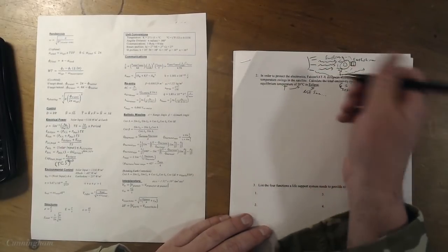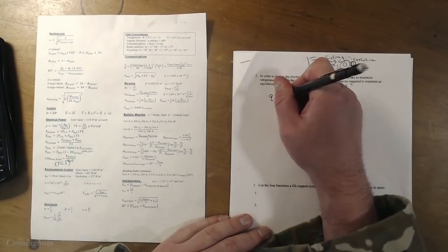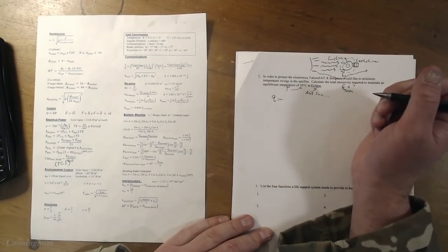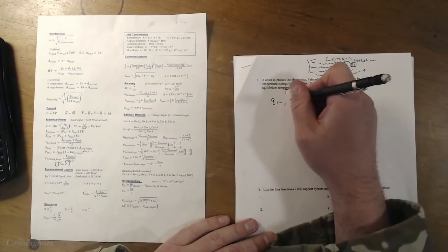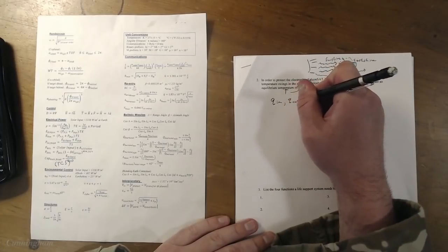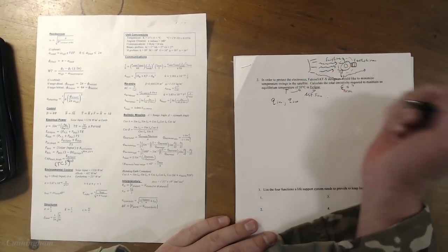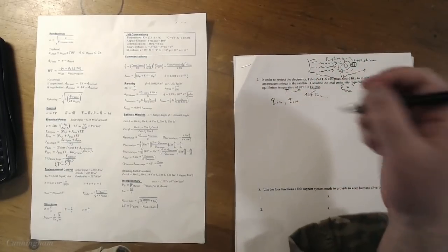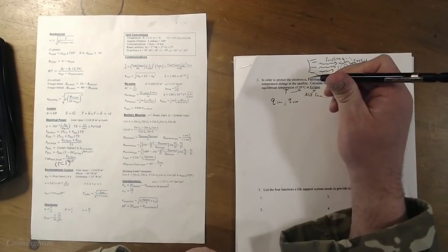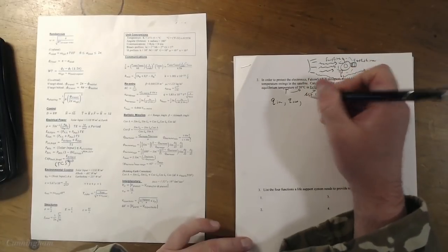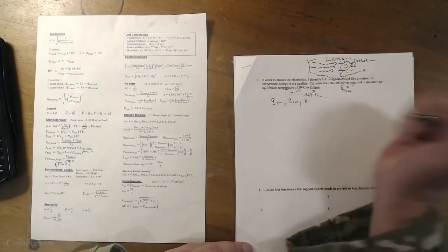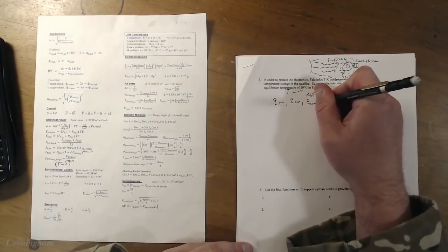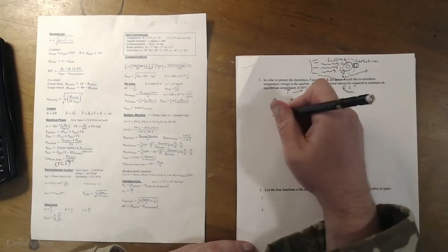So let's begin. Our process looks the same. We're going to find how much heat overall is coming into the satellite, how much heat needs to go out from the satellite, because remember, Q out takes into account all the heat generated by the onboard electronics and machinery and reaction wheels and all that. And instead of finding temperature like before, we're going to find emissivity total. That's what we want. So really the process looks almost exactly the same. So okay, Q in.